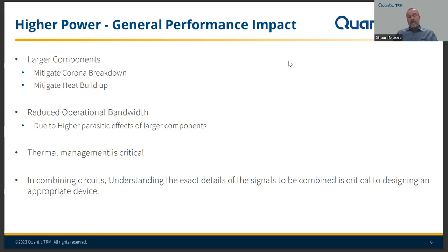So it's a real struggle, and it's a real problem that we have as devices want more and more bandwidth at higher and higher powers. Very often you find yourself at odds being able to build a part that will survive the power and also accomplish the bandwidth. We need to make sure that we can get the heat out of it. Therefore, on certain designs, we no longer rely on just passive heat mitigation. Very often we have to have liquid cooling or fans or other sorts of heat sinks in there to get the heat out of it.